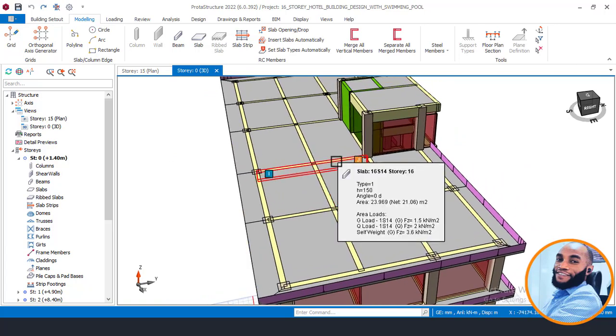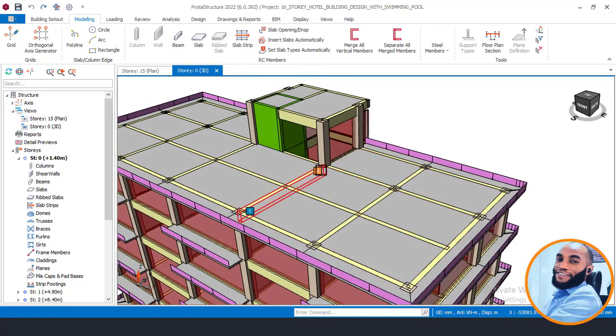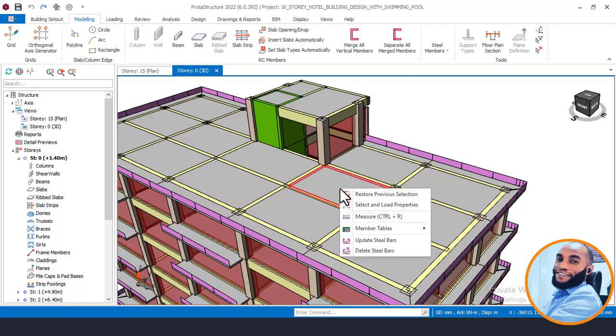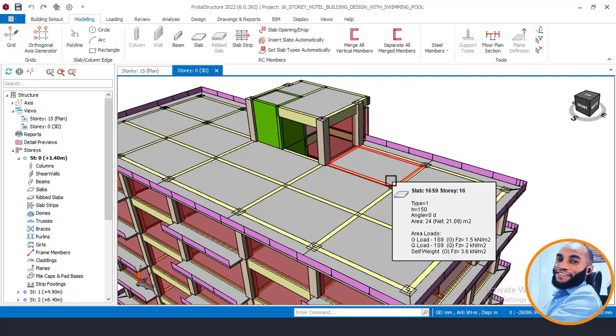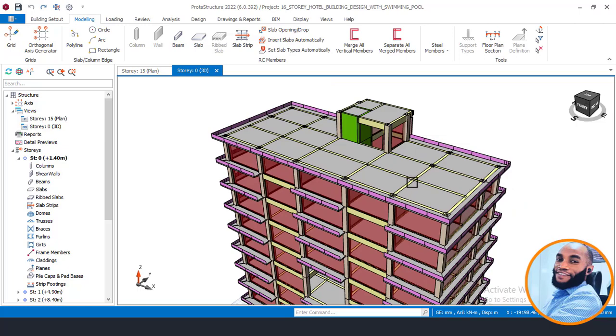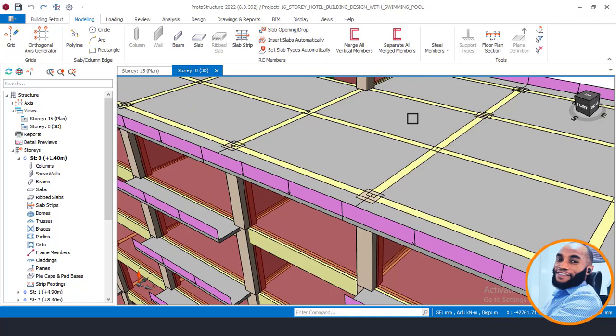Now, roof slab comes in two types: one-way rib and two-way ribs. Two-way ribs are often called waffle slabs, and waffle slabs are very good when it comes to live load reduction. Also, it's good when you're designing for a very large span of a slab. Okay. Right now, although we are not designing for a very large span, I'll limit waffle slab just to reduce the load for the building. Now we are going to change this solid slab to waffle slab.